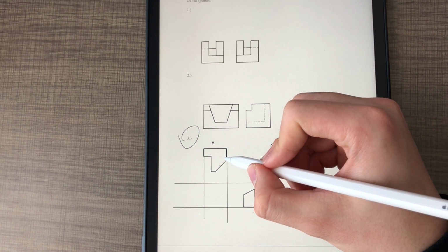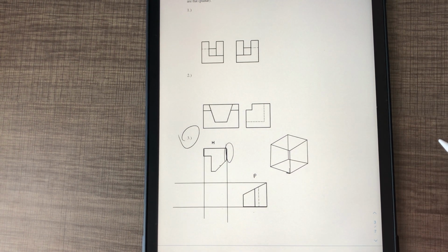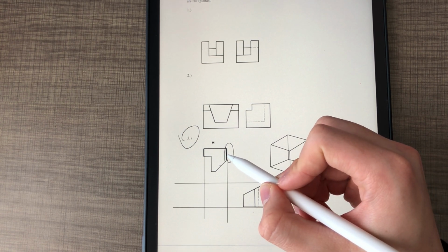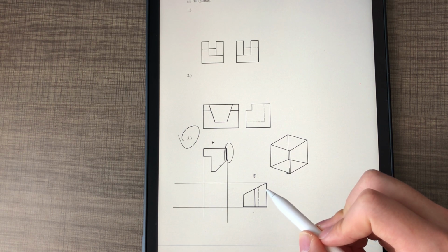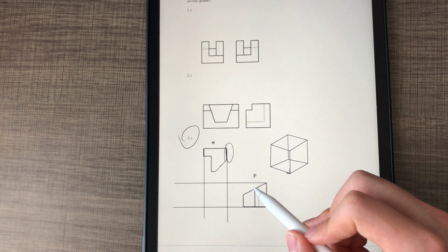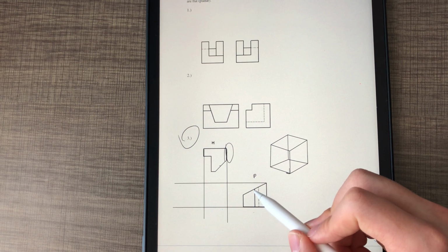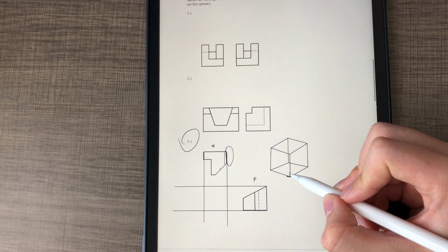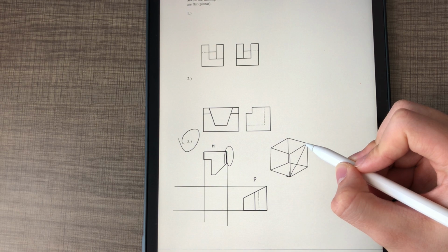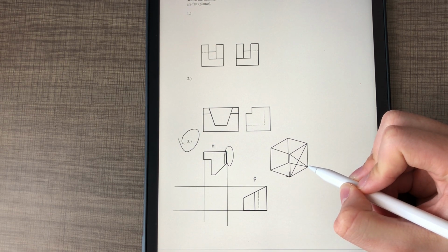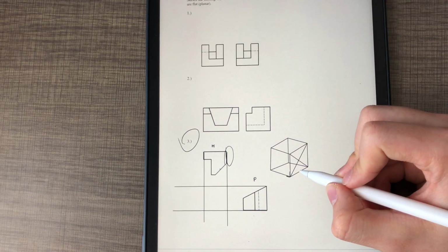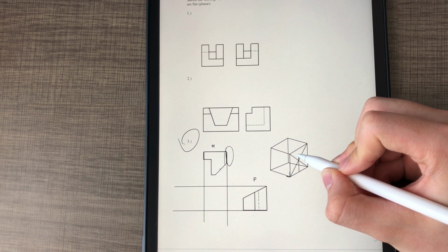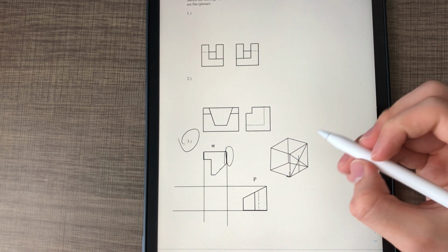So in fact, I have something that's pressed right up against the wall, and I can just draw that right away. So I know that this one is pressed right up against the wall, and it's shaped something like this. And I can take those dimensions exactly. So I have this thing over here halfway across the feature. So I'll take construction lines, drop diagonals, and I can use this height exactly. So I'll trammel that height up. I won't actually trammel it just because I'm going quickly. So I'll take this height,